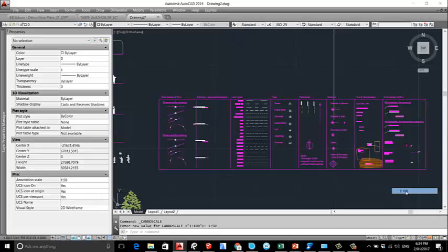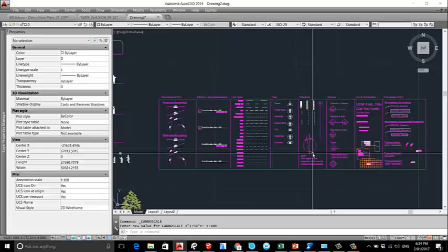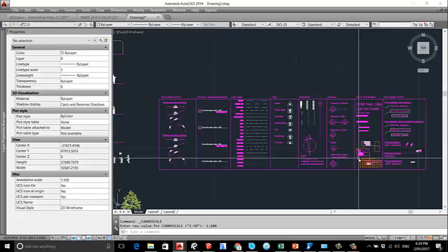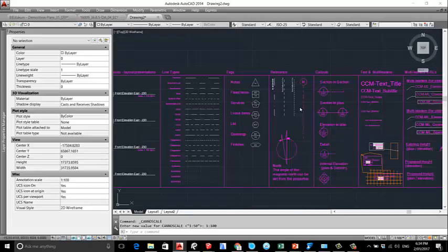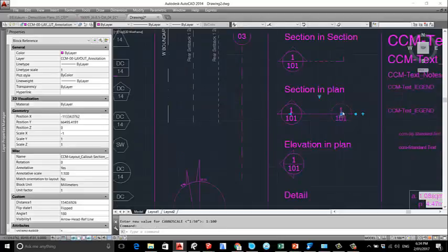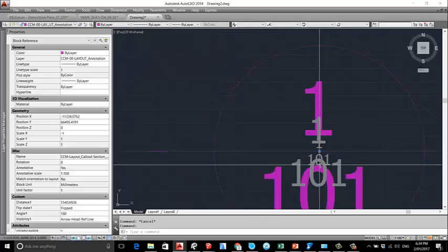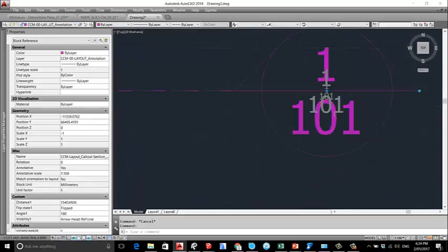Now, AutoCAD has this thing of annotation, annotative scales, I think from 2004 or something like this, and it's misused. It takes a bit of resources of the drawing. That's the only problem, and sometimes it gets a bit messy. For example, if I now touch this one, it will show the scale and also two more scales that have been set up for this item.